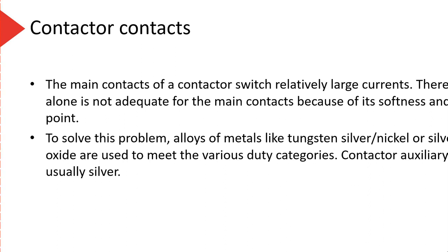And that's, I mean, it's neither here nor there. One of the advantages of this type of switching, as opposed to a normal light switch, is that it happens very quickly. We have the magnetic mechanical action in there that shuts the switch, and then when that magnet turns off, there's a big spring in there that pushes the two parts away from each other. So it happens quite fast, which minimizes the arcing.